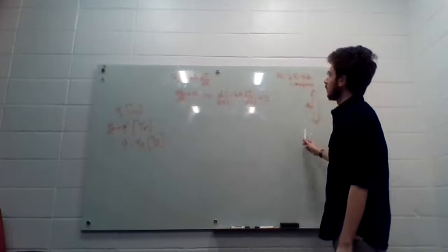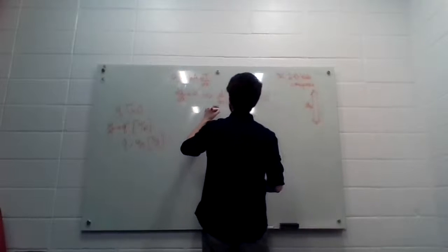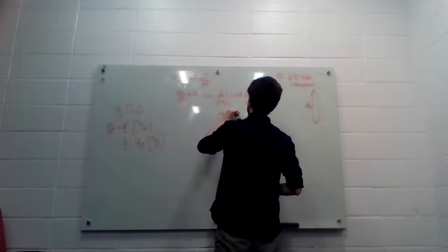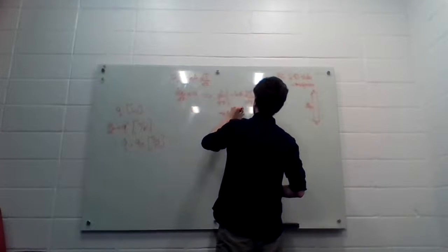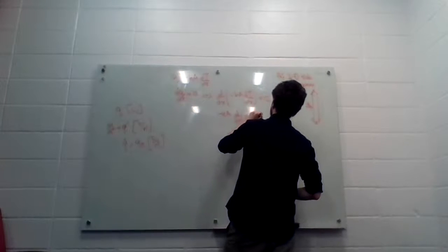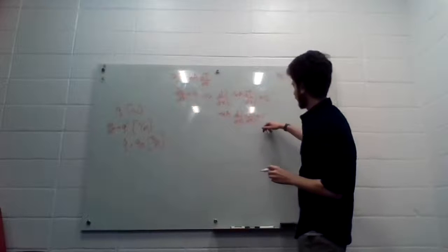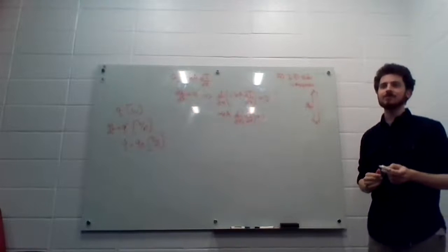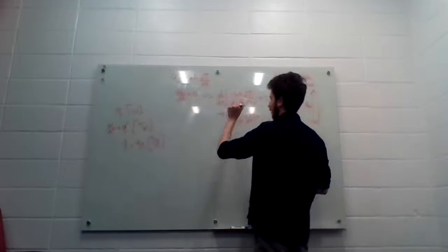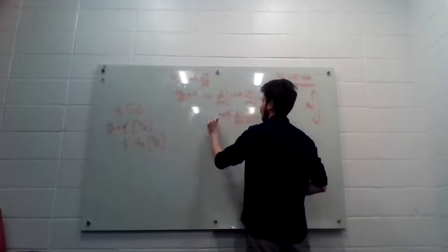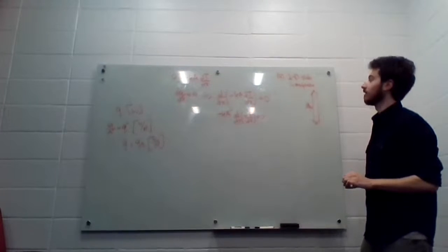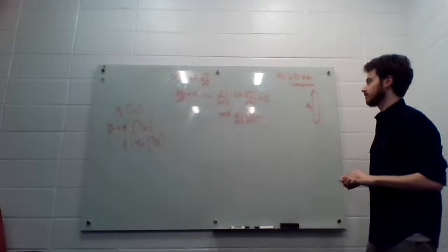So we can take both of these terms out. We've got negative K A d/dx of dT/dx equal to 0. What was the thing I said before? Zero is on the right. You can divide it by anything, right? So we're going to divide it by negative 1, K, and A. We just strike all of that from the left-hand side. So now we've got d/dx of dT/dx equals 0.